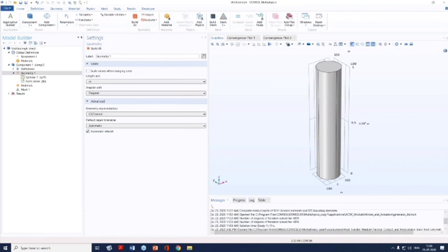Can I draw geometry in motion? Interesting. See, the geometry that you are going to draw is a fixed geometry. You can provide motion to that geometry, let's say directly by using the moving mesh technique. Or if you want to see a parametric analysis, like at one certain position, what is the result, then at the next position, what are the results, then in those cases also you can use the parametric sweep operation.